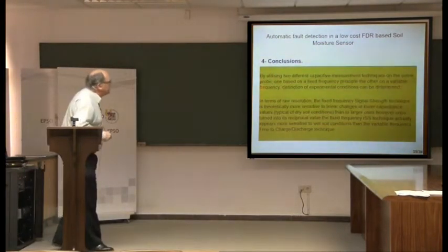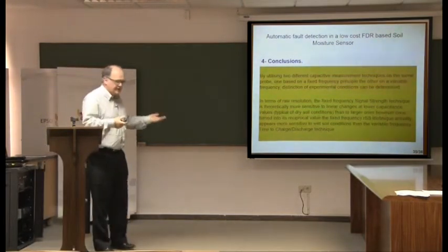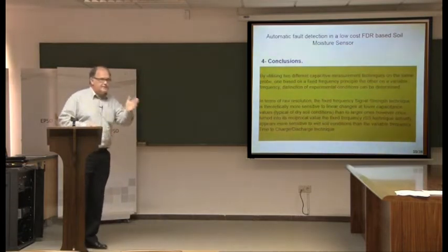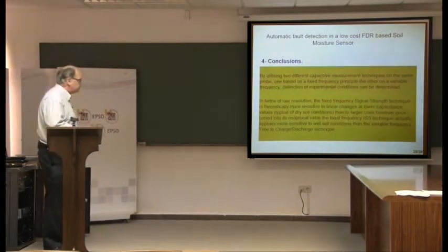So in conclusion, by utilising 2 different capacitive measurement techniques on the same probe, one based on a fixed frequency and the other on a variable frequency, we can see a distinction of experimental conditions. We could tell the difference between the capacitors and between the soil. And what I'm hoping is that as we try it in different types of soil, we may well be able to get some indication of the properties of that soil type.